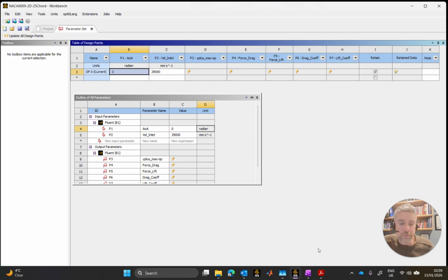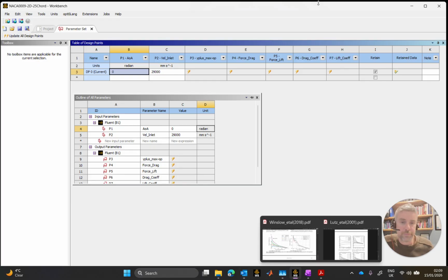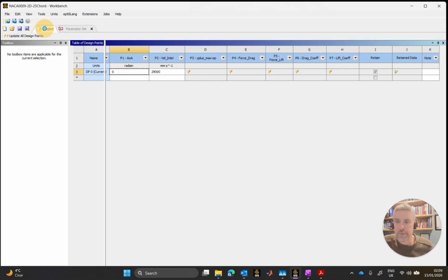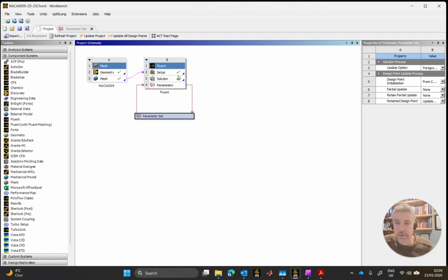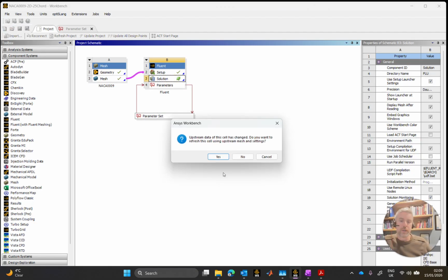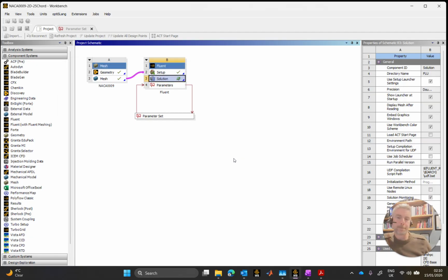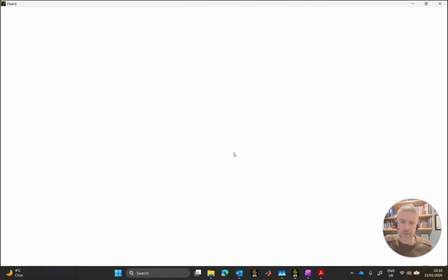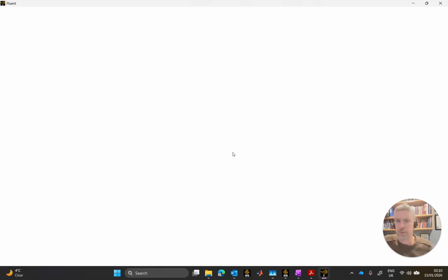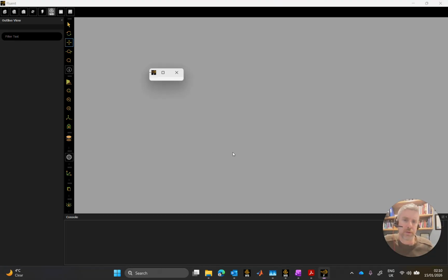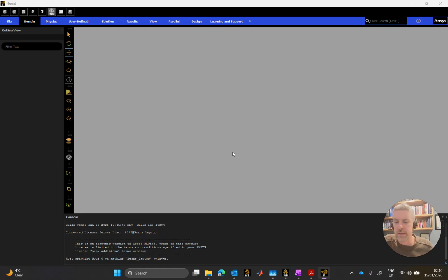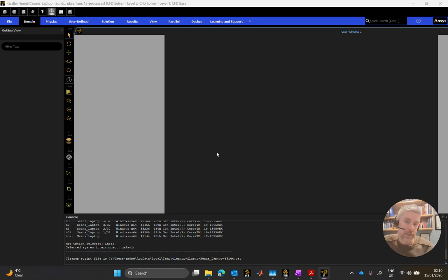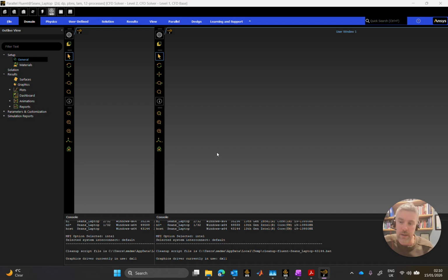What I should have done before I closed off Fluent is reduce the number of iterations that I need to undertake. Let me just do that, please, because I have it up at 1,000, but it's converging much sooner. It's converging there around 300. Having a look at the residual traces, I have taken off the other convergence conditions as well, of the drag force and the lift force.